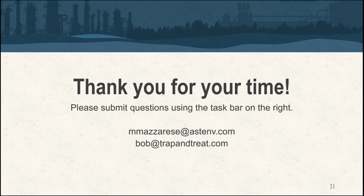Mike talked about this from the overall concept of the technology: the transport mechanism is groundwater. In the smear zone at that site, that zone was not saturated 100% of the year. So you don't have intimate contact and the overall absorption of the mass into the groundwater and onto the activated carbon. The power, though, of the product once it's in place is that it's going to continue to manage that mass.